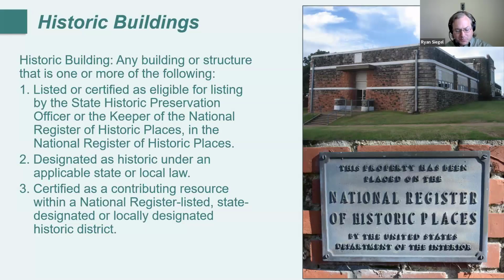And for Illinois, if it is a listed building or designated by the authorized personnel, you don't have to deal with code compliance. If you do have to submit for it as part of your building permit, if you are working on a historic building, you would list that as an exempt project from the energy code. So again, if it's eligible for listing, or if it's contributing as part of a historic district, that is still going to require some code compliance for the energy code.